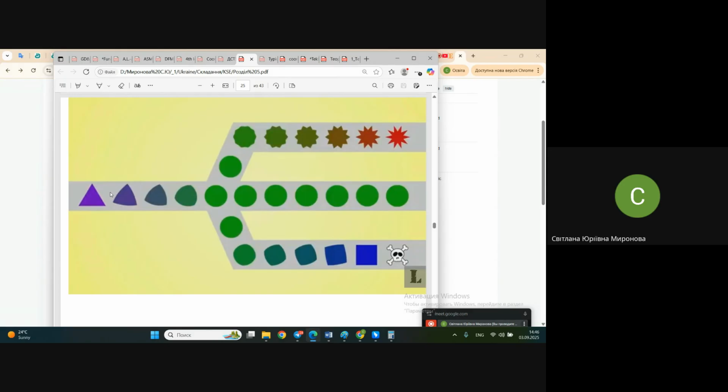It's a combination of theoretical loft and origins of information, which looks practically like an assembly drawing, but on a special carrier. Next, you copy it into a control print. And in case it was the traditional loft template method, from control print you make templates of jig, templates of tooling, templates of whatsoever. Control print is the origin of coordination here. It's a sort of loft once again.